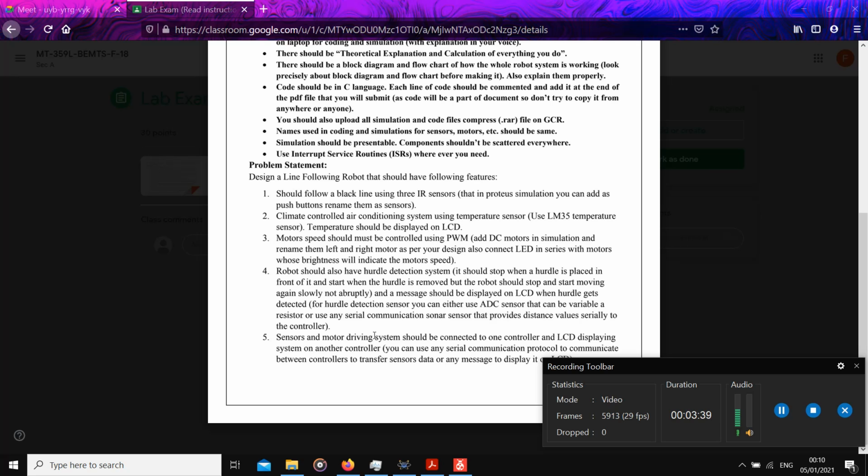One of them is the master, and the other acts as a slave. You can do it with the help of SPI, UART or USART, or I2C. The master takes and gives commands to its slave, and the slave is generally connected to an LCD, and the LCD displays whatever information it has to take from its master controller.